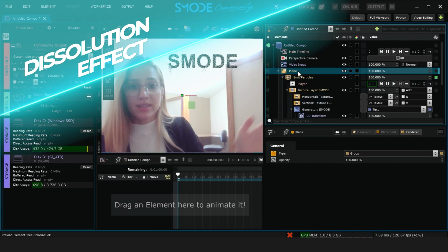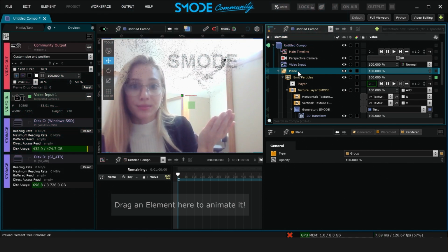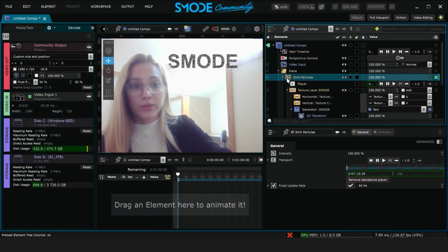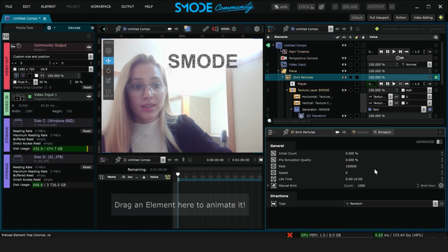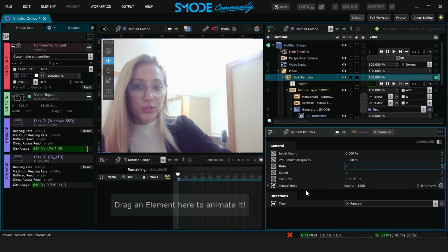Currently, the problem is that even when the text is dissolved, it will appear again behind. To avoid this, we will go into the particle emission settings, and we will change the emission rate to 0, and choose to emit particles manually whenever we want.